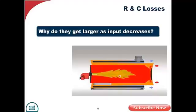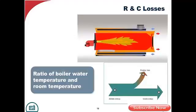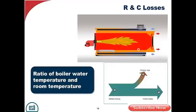Well, regardless of where I turn this burner down, that temperature is not going to change. So as I decrease the firing rate, therefore the input, I'm dividing into an ever smaller number. So therefore the radiation and convection losses climb inversely to input.